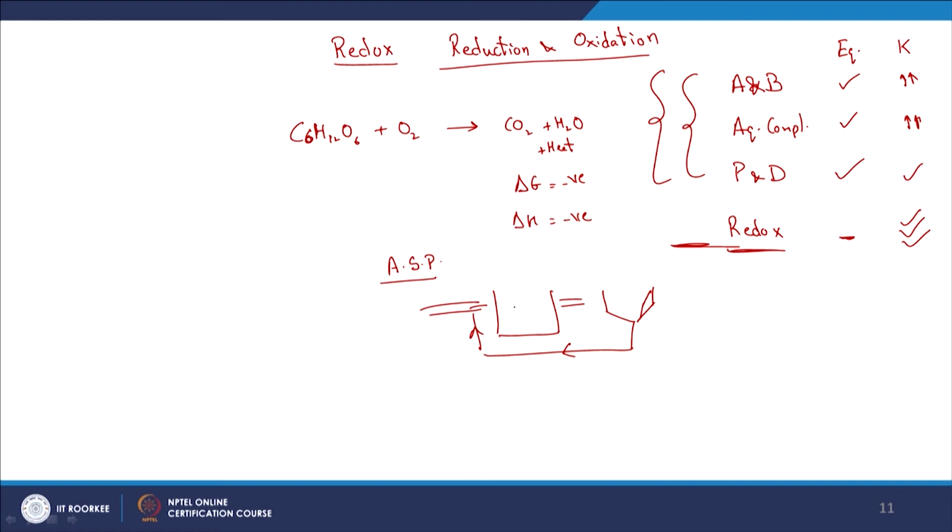So here in this activated sludge process, this particular tank, which is always well mixed, what else are you supplying? You are always supplying a source of oxygen. So why is that? And you also have organic compound here, which is the waste that you are trying to degrade. Organic compounds are usually in the reduced forms. And why are you supplying oxygen? Because you want to oxidize this particular organic compound. And obviously this is the relevant reaction here.